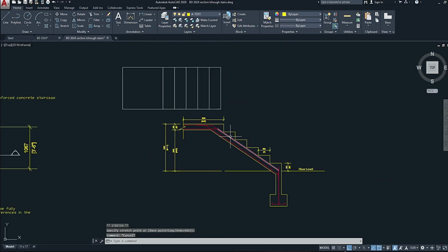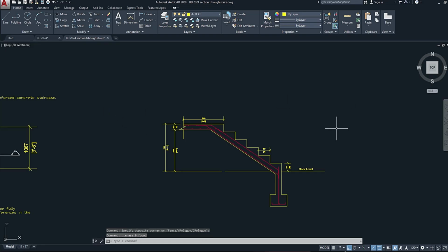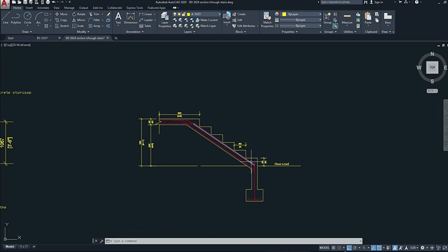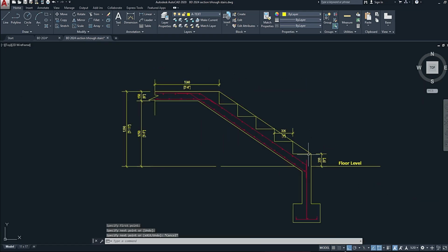Okay, all right, so let's add our railings, because that's basically the only thing outside of labeling the steel components. All right, because we need to add those. Now, what are we working with the stairs? All right, now typically we'll set that at about 900 to 1000 millimeters. Again, same way in which we draw, we offsetted this line here. We're going to do the same thing for the railings as well. So draw a line across like this, and then you offset that by your 900 to 1000. I'm going to use 900 in this instance.